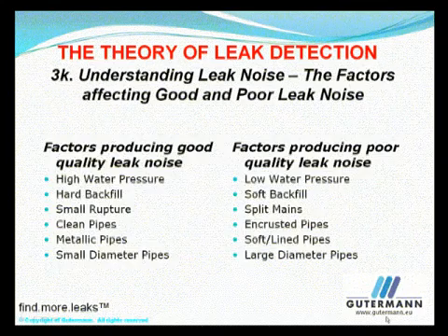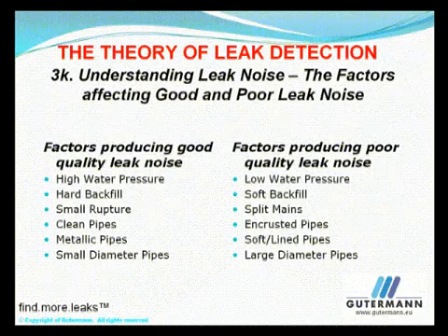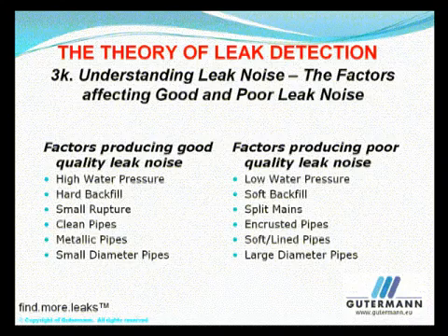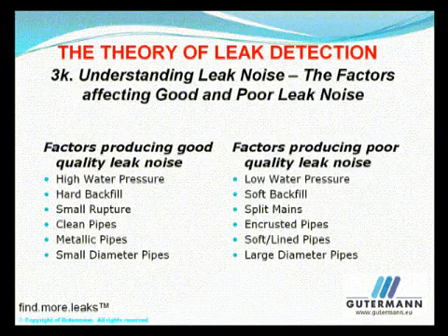The factors affecting the properties of leak noise are: high pressure makes a louder sound at a higher frequency than low pressure. Hard and sandy backfill create a louder sound at a higher frequency than clay backfill. Small pinhole leaks make a louder sound at a higher frequency than a pipe with a broken back, whilst longitudinal splits create very quiet leak noise at low frequency.